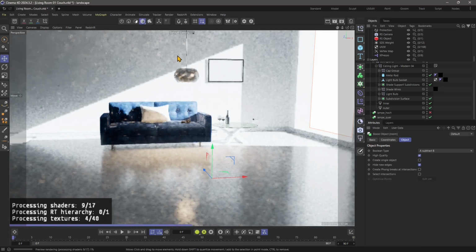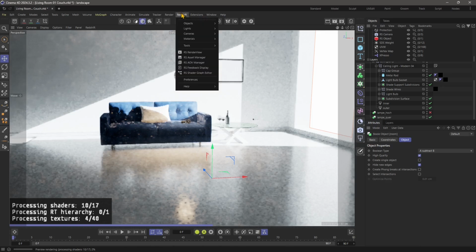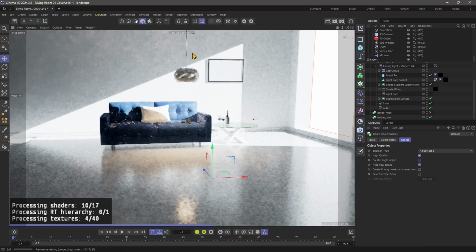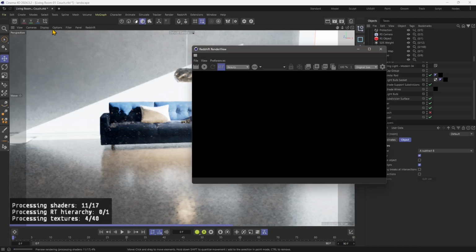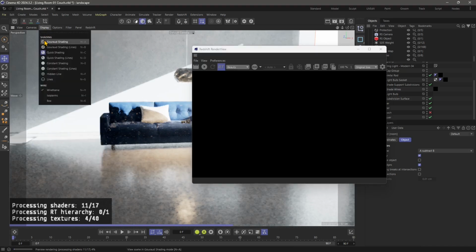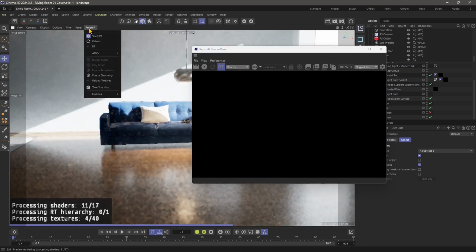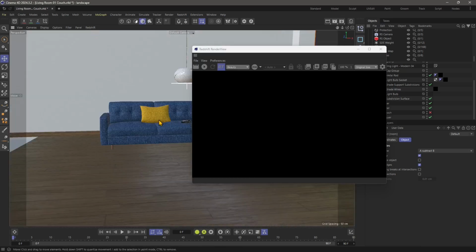Now you can see this interior is a combination of kind of a sunlight coming from outside, and then we have a lamp. So we can simulate something similar using only Redshift assets, only Redshift lights. If you want to use the render view, we don't need to do the render twice.